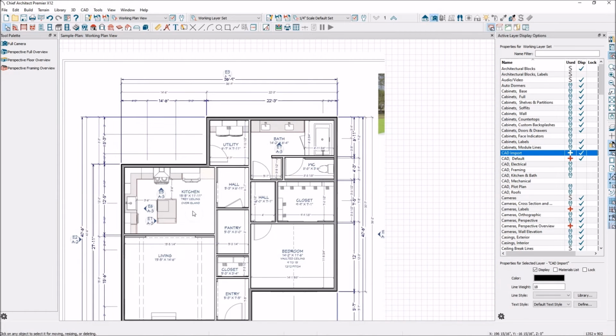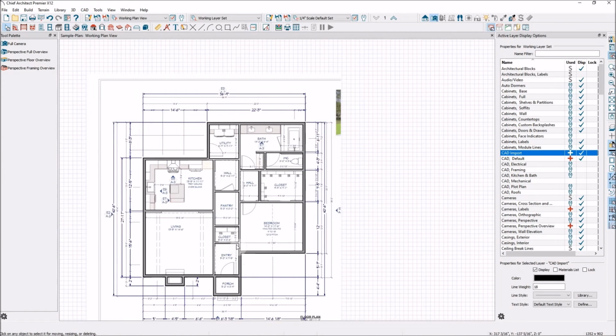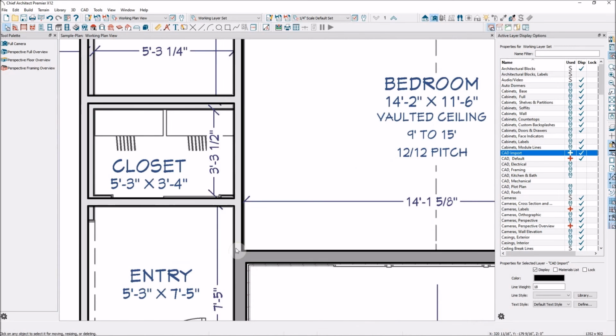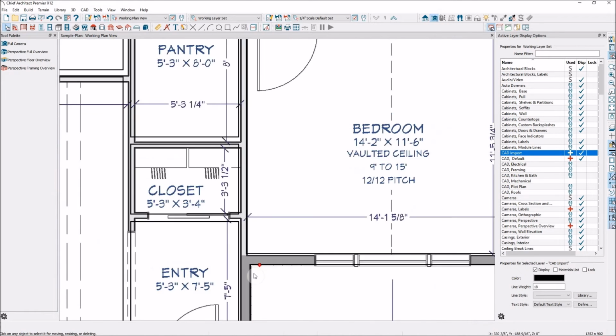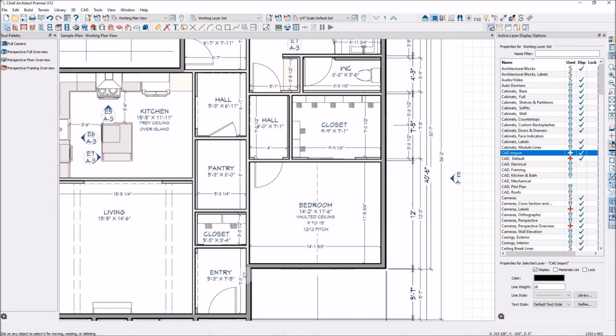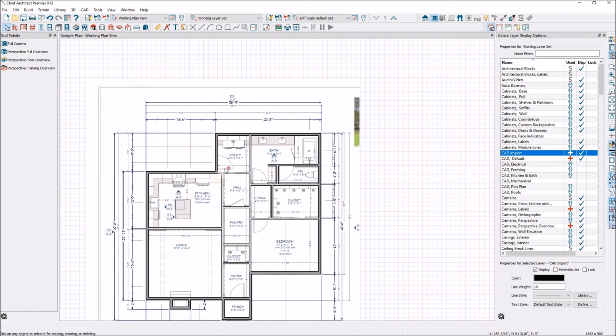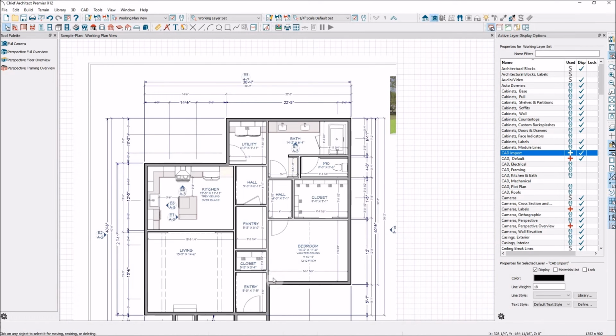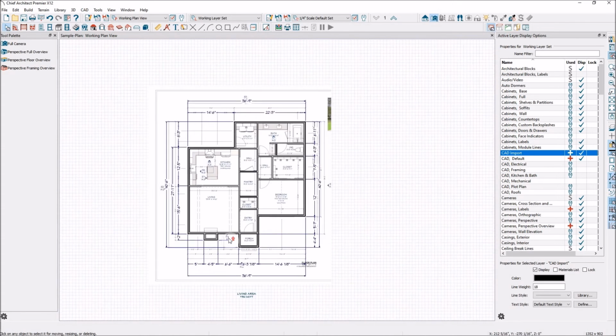Okay, so this wall here and this wall here connect exactly to these exterior walls. When I drew those in, I grabbed that and snapped it onto that, so that is lined up. And this one too. So these two walls are not going to move. Those are set where they are because they're connected, coming straight off of those walls.